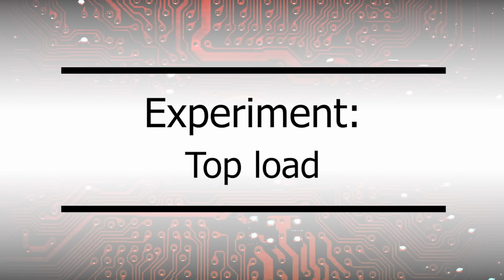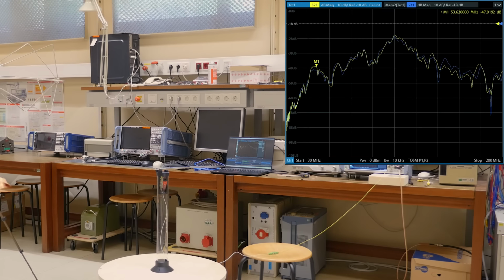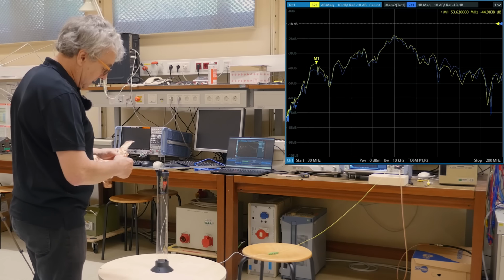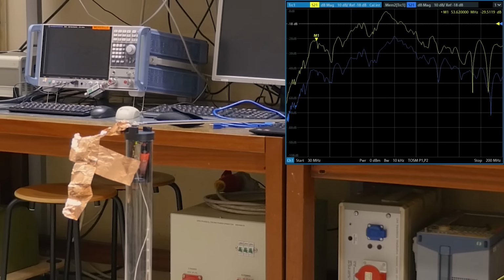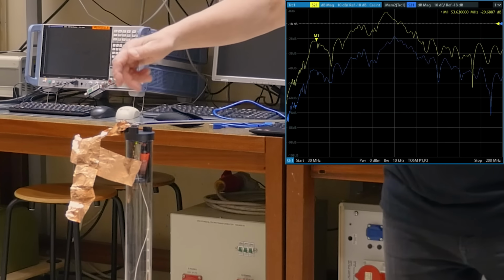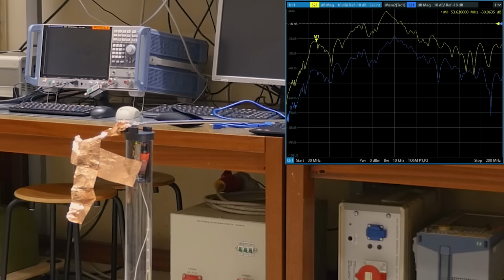Okay, so we are back to a setup where we made the side very, very short, so not a lot of current can flow here. The other side is fully extended. If we put a larger piece of metal on this side, of course we expect that much more current can flow because there's a lot more capacitance. So now we added a top load here for a dipole, what we call the top load or monopole. So we added some metal here. The metal allows more current to flow in this direction. So we have more current flowing this direction. And we see the signal went up by like 15-20 dB.